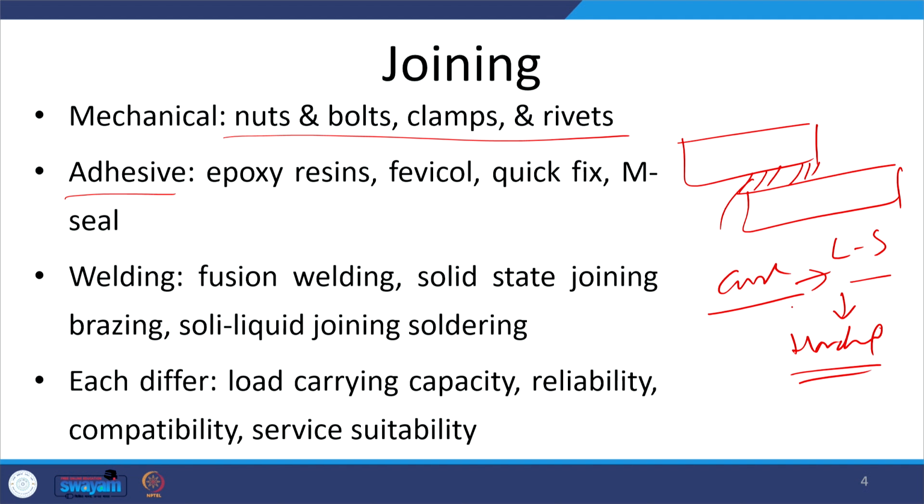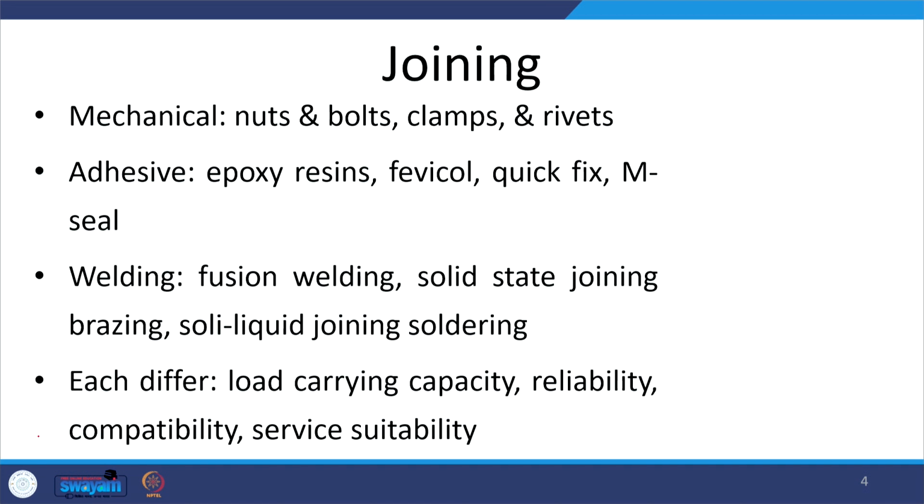Hardening will be happening in both the cases where a liquid to solid transformation takes place, in the case of thermoplastic based adhesives or thermosetting based adhesives, where some kind of chemical reaction is also involved during the curing. That in turn will be leading to the development of the joint, which is reasonably good, not as strong as that of the fusion weld joints or the mechanical joints where nuts, bolts and rivets are used.